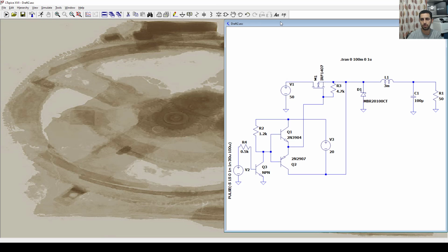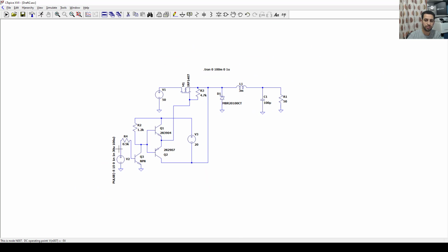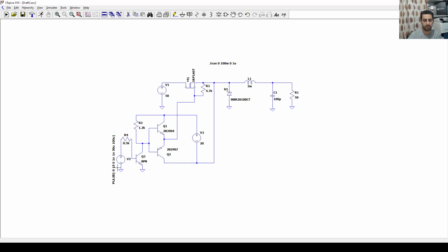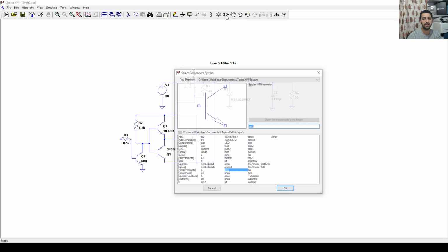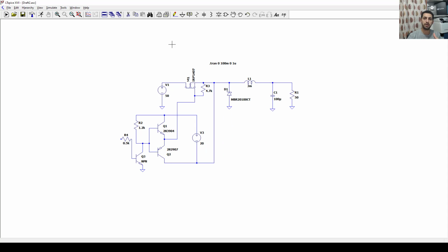So now let's just close this one and maximize this one. If we want to drive any system, we have to generate PWM here, okay? And that generator is considered as a programmable generator. But in LTSpice, I will replace that with a circuit. So I will maybe remove this one and bring here a generator, and that generator is different from what we used to. PWM can be generated by using a comparator. And that comparator will compare a triangular wave with a voltage, maybe steady voltage, and that voltage will define for me the duty cycle. So I will show you what I mean here.